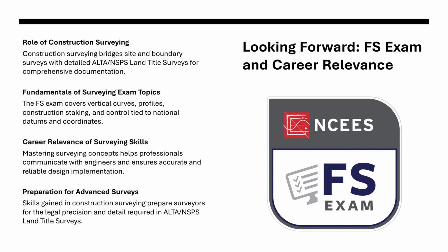If you can control a site well enough to stake alignments and profiles, you will have the skill set to document improvements and tie them back to property lines in an ALTA deliverable. Think of it this way. Your boundary surveys establish ownership. Your site surveys capture existing conditions. Construction surveys bring the design into the field. Your ALTA survey integrates all three into a comprehensive legal and spatial record.